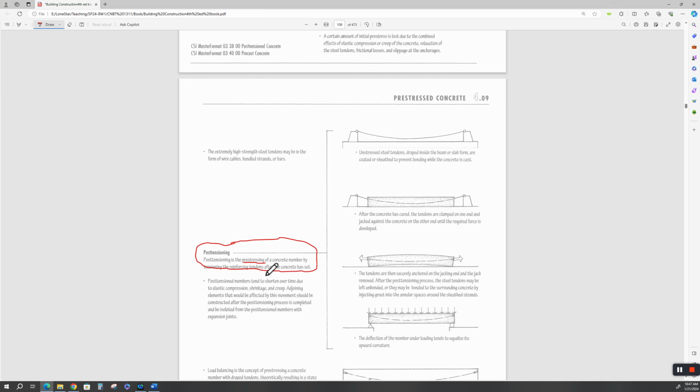I don't know why he stuck that in there. Post-tensioning is after. This stuff is not under tension yet. And if you watch those videos, you'll see how these tendons are laid specifically over the high stress areas and the less stress areas, so that when it is stretched after the concrete's poured. So now the concrete's poured.